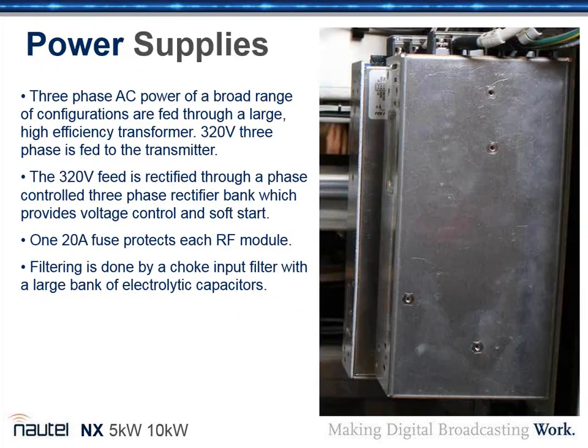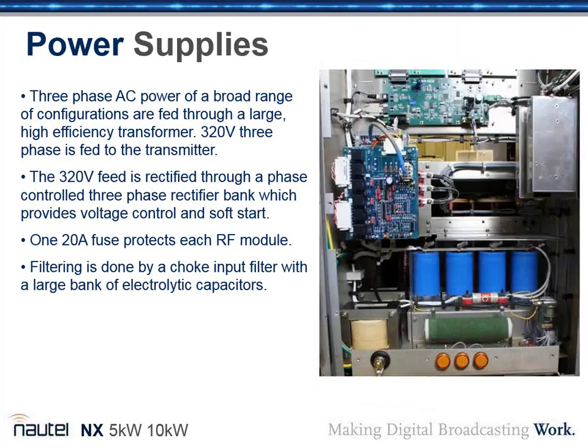Okay. So we've got a couple of power supplies for the low voltages. One is 48 volts and 15 volts? That's right. Okay. And those are SMPSs, switch mode power supplies, that are fed from the output of the transformer. So you get the benefit of the transformer in terms of surge protection. Yep. And then you can see how the whole power supply system works.